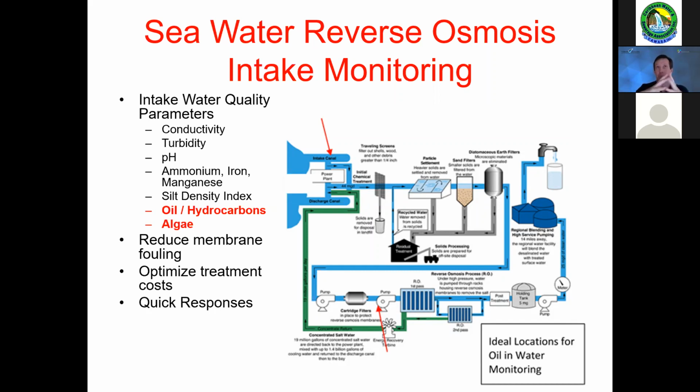The membranes are usually all installed in parallel, so the same water is delivered to all the membranes. There might be a second train of membranes that treats the reject water to get some more salt out of it, so the water would eventually go to those in series.